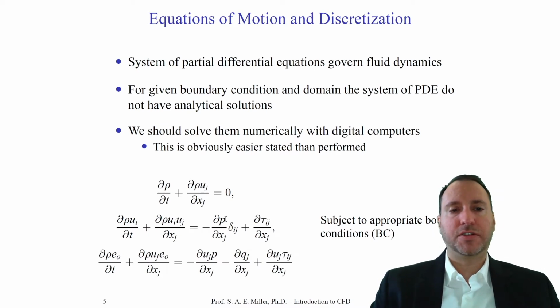So that's the internal stress of the fluid. Tau sub ij is the stress tensor, so that's the stress on the fluid's surface in the normal and shear directions. So if i equals j here, it's in a normal direction. If i and j equal 2, for example, it'd be the normal stress in the y direction.